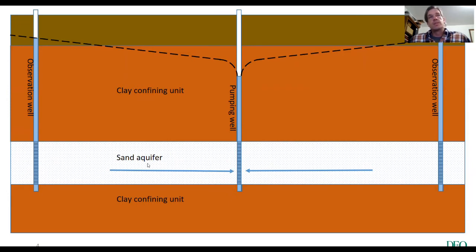And the rate at which the water travels is dependent on how hard you're pumping the well, and also the ability of the materials to conduct the water or allow the water to pass through. And also how severe the gradient is. If you have a high pressure gradient, the faster it's going to want to be pushed, basically, or the steeper the hill, the faster the ball can roll down.